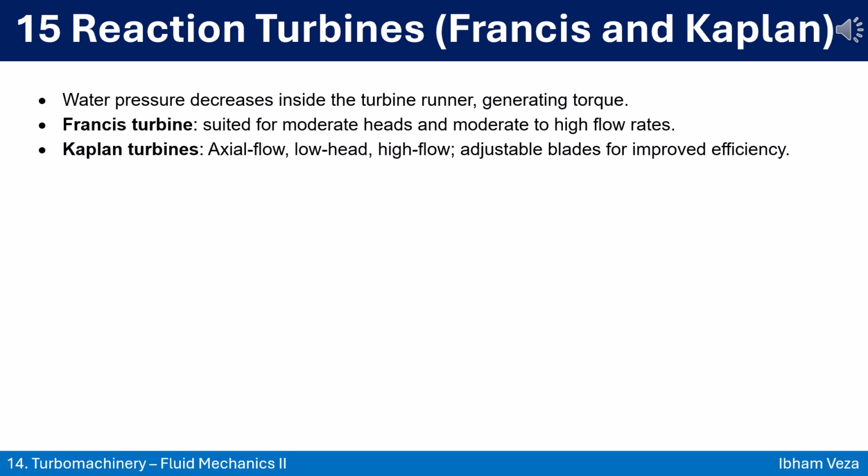15. Reaction turbines, Francis and Kaplan unpacked. Imagine water rushing through a curved scroll case, the pressure steadily dropping as it threads each blade of the runner. That drop in pressure is the engine of a reaction turbine. The water gives up its energy right inside the wheel itself, turning pressure into torque.